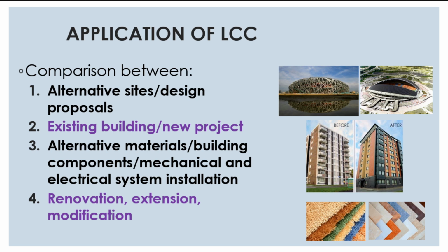So what is the application of life cycle costing? So the first application is, number one, is to when you have different sites or different design proposals. So either you want to construct a building by using design A, or a little bit more complicated, design B. So design A and design B, which has the lowest overall cost.